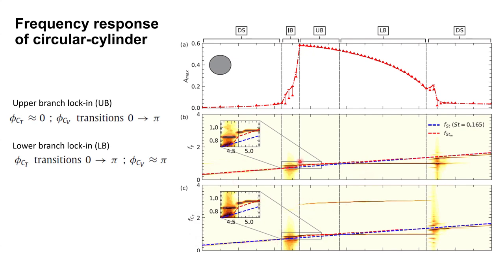Okay. So this is two data sets I'm plotting. I'm also plotting the so-called Strouhal frequency. So this is a frequency which a cylinder will exhibit if it had been stationary. So just a Strouhal law or vortex shedding Strouhal frequency I'm plotting. It will appear as a straight line, as you can see here. I'm also plotting another red signal, SPM, which is for Strouhal frequency modified, which we'll discuss in the next slide. But right now, just keep in mind I'm also plotting it together with this.